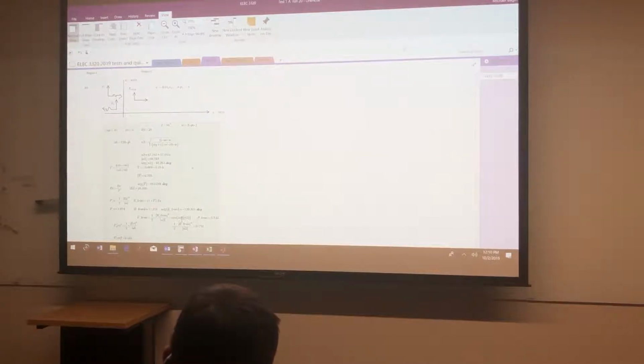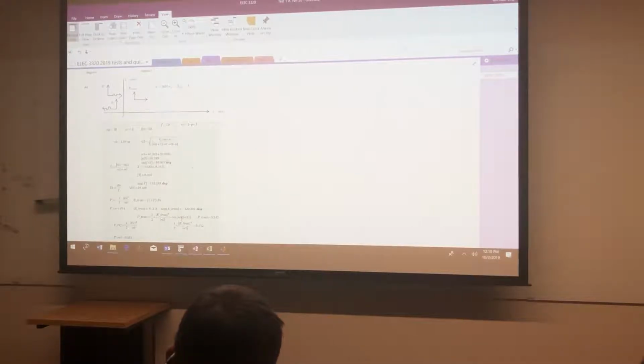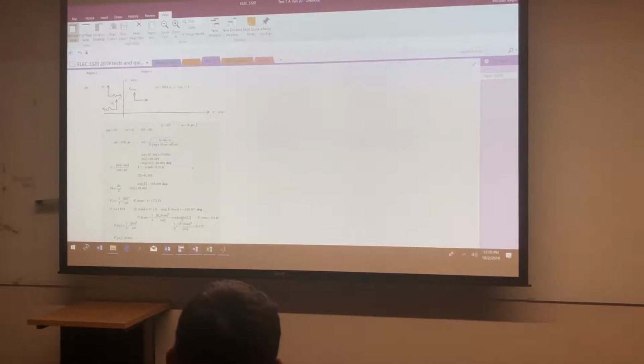Remember the cosine of the angle? It cost people a point. A lot of people did not put that in there. Does everybody follow me on this class? You have to have that cosine in there. And if you did 1/2 real part of E cross H conjugate, you had that automatically in there. But people didn't, I only know of a few people that used that formula.